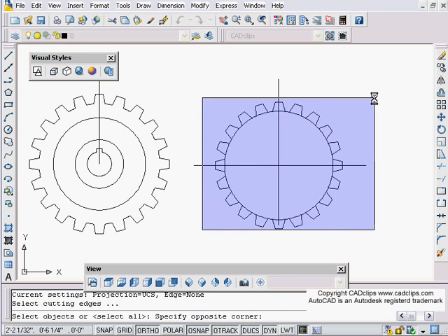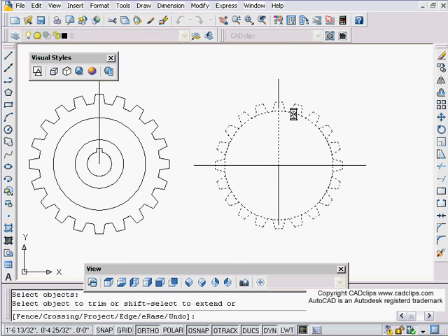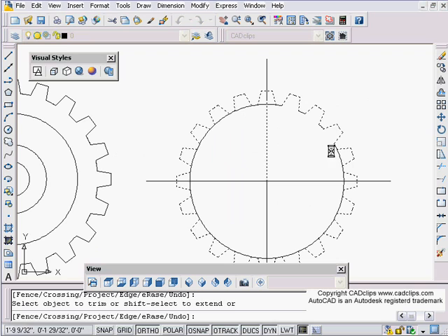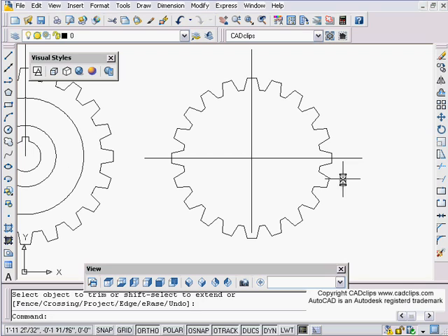Okay, now I'm going to do a trim. All these objects, enter, and I'm going to do a little bit of legwork. Not a big deal. And work our way around, and then we'll take all of these objects and join them into a polyline, and then we'll extrude them out. Okay, so we can have a look at that. Maybe draw another circle in.